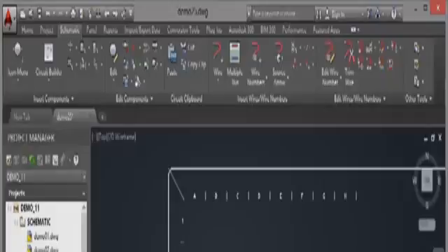Specify a start position, say there, and you'll notice this time there are no reference numbers on the actual ladder itself. That's because you refer to these here. So you've got B3 will be there, and so on and so forth. Ideally, what you want to do is you want to set up your ladder so that it actually ties in with the coordinates and the spacings. Now, I haven't done that in this case. You can see that that ladder does not tally up exactly with any coordinates on that XY grid.